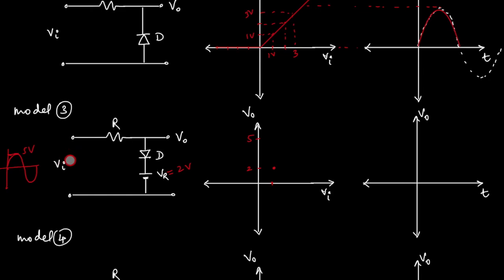But actually what is happening, see, 0 volt will start, and it will go 0.5, 1, 1.5 and so on up to 5, correct? When it is 1 volt, it is forward biased, means it is short. But this 2 volt is sitting here, right? When this is short, it means this wire is connected with this potential. This potential is plus 2. So plus 2 is sitting here. So when 1 volt comes like this and 2 volts is already sitting here, what will happen?